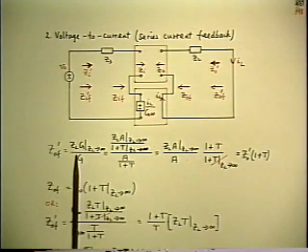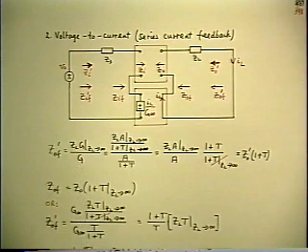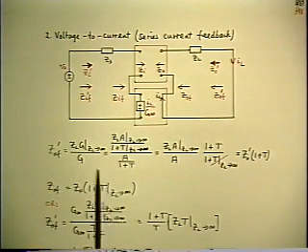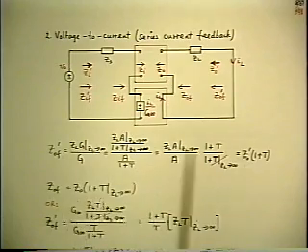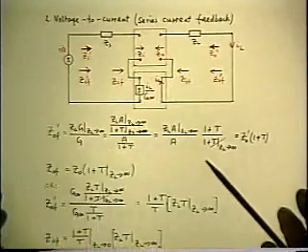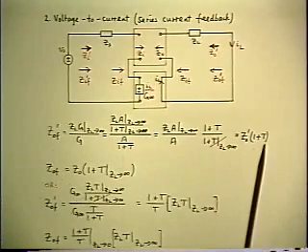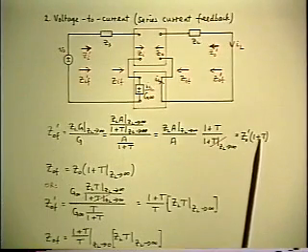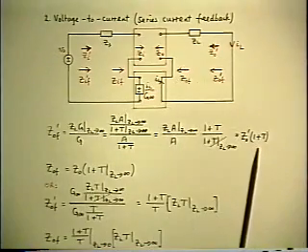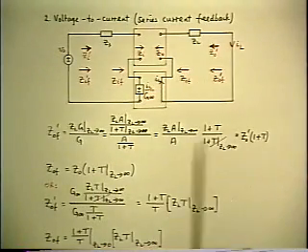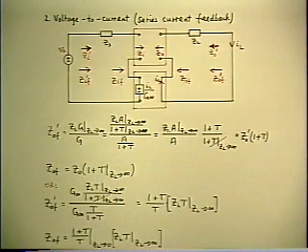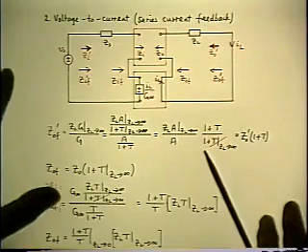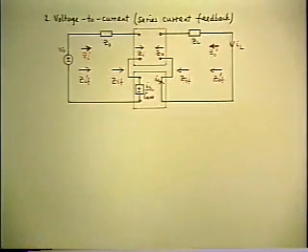Well, since the formula is the same, all of the things that we derive from it will be the same as well. So it's hardly even necessary to write it all out again, but I've done that anyway, just to be complete. The net result is the output impedance with feedback is bigger than the output impedance without feedback. And you get the same four results, and the same interpretation, of course, that goes with all of them. Okay? The input impedance formulas, of course, are identical to the ones that we've done already.